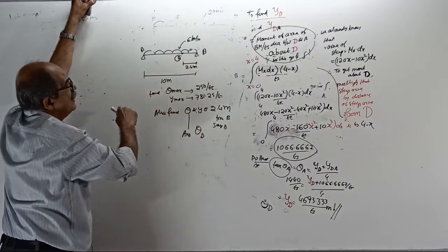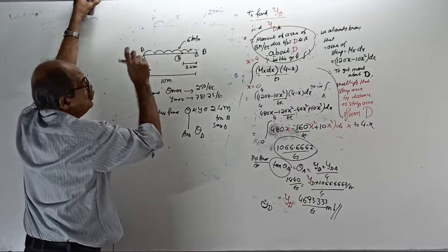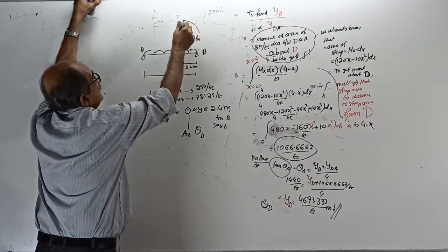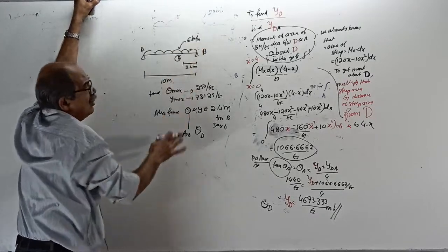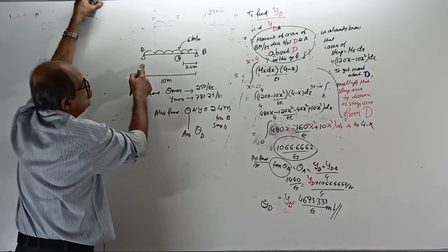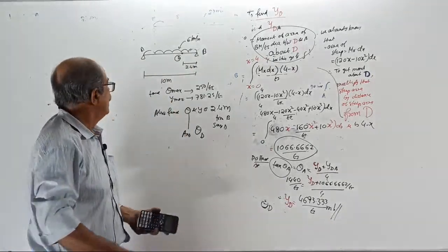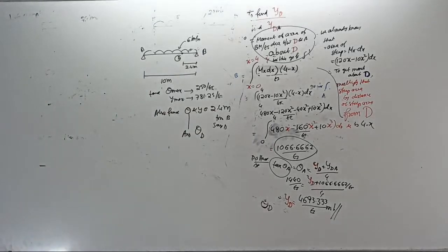Can you solve? To get slope at D, theta B minus theta D. To get deflection at D, what you do? Then the area will come this way. See this area. Again, you take x from B and correctly solve. Or you can take 2.4 from A, same answer will come, but no, you do from B. Can you do it now? As a practice, to get full control.